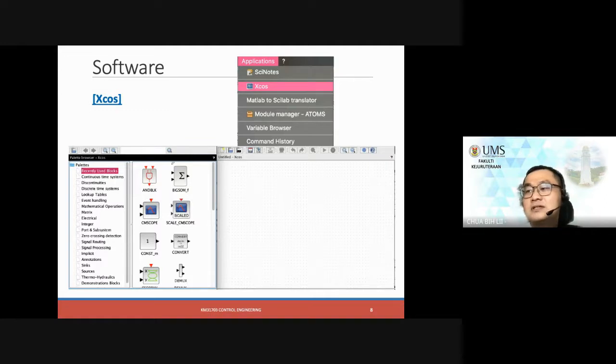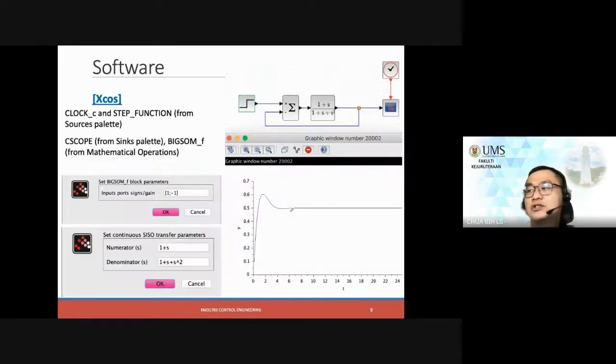This is a summing point: two values, totaled up together. With the summing point, you can show the graph of how it would respond. You can insert a signal, a constant value of 1. If you insert a constant value of 1, it means you are putting in a step input, right? This is how you can insert all these things. You just click, look for the typical block diagram, and drag and drop. Then you will be able to run it.